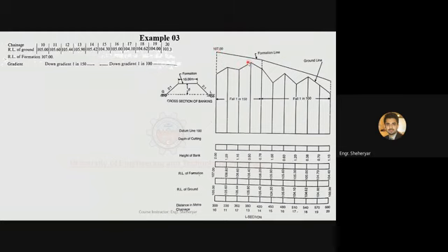Again, you can see that here the ground level is below the road profile, because you have to provide a smooth surface to the vehicles. So you have to maintain a uniform slope throughout the road profile. So again, you need to fill that portion, but the amount of filling required at this point will be less as compared to this point, and so on. If the ground profile was above the formation level,